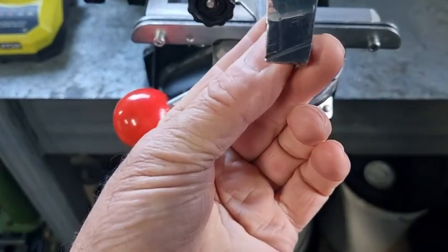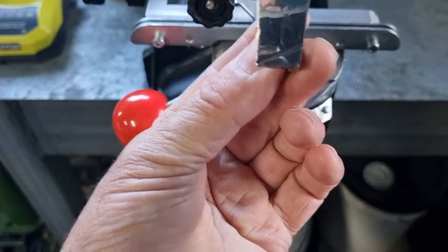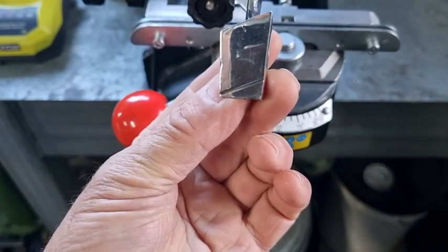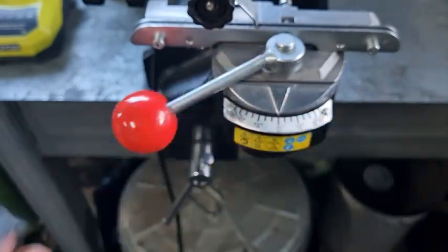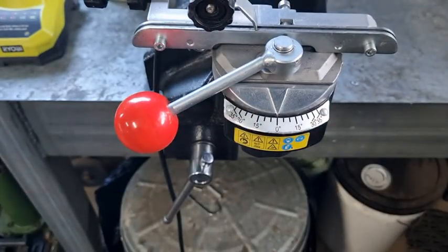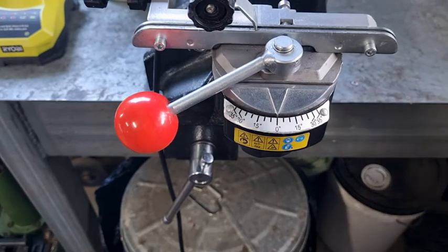this point becomes more pointy as you go 35 degrees. And the more aggressive you go on that angle generally means that it'll get blunter quicker. So that's the trade-off. You go a more aggressive angle, it'll cut faster, but it will blunt quicker. And that's why 30 degrees for the top plate angle works out really well.